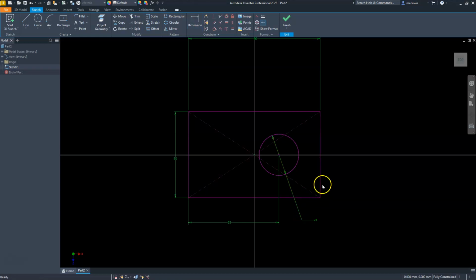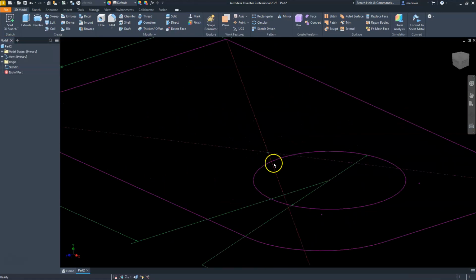All right. Now I'll put the fillets here as well. Usually I like to make those features, but I'll use it here. So fillet 15. One of the hardest things you have to try to trick your brain from doing is selecting the enter button as you would do in AutoCAD. Here, once you invoke it, just start selecting your lines. Now this is all I need to do for this sketch, so I'll finish this.